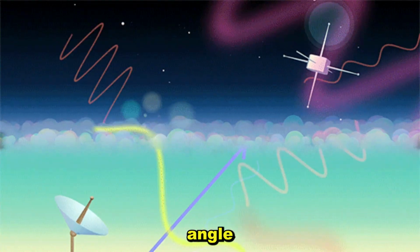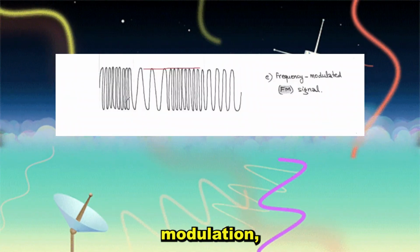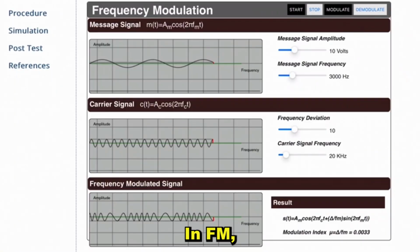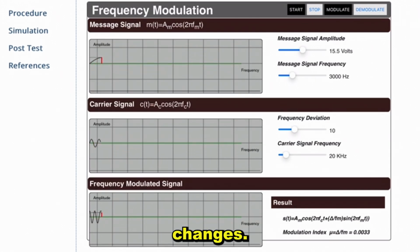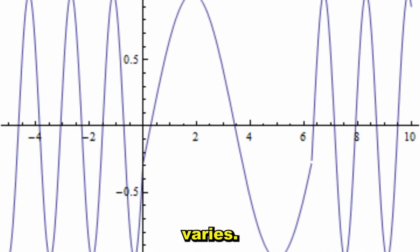Next, we have angle modulation. This type includes two main forms: frequency modulation, FM, and phase modulation, PM. In FM, the frequency of the carrier wave changes according to the information signal amplitude. So as you can see, when we change the amplitude of the information signal, the frequency of the FM signal changes. In PM, it's the phase of the carrier wave that varies.